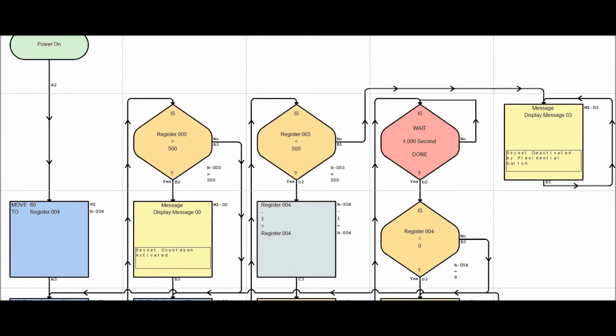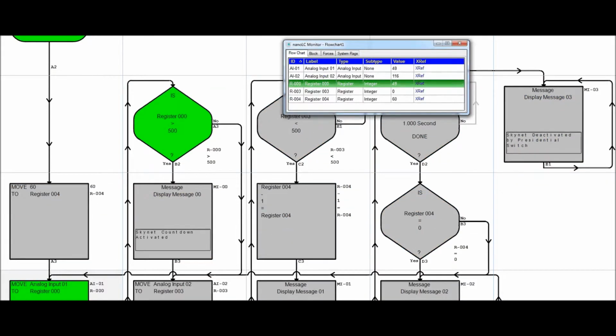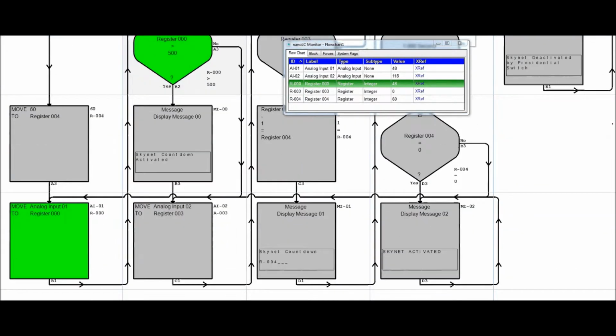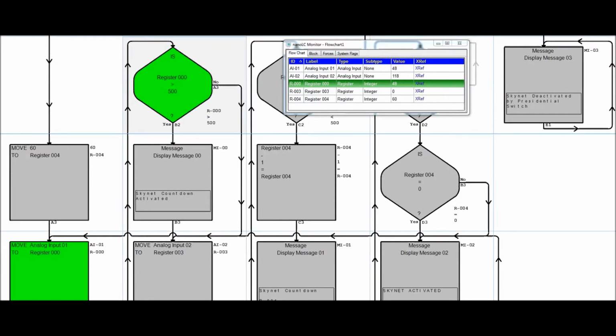So up at the top, you need to click download and go once you have it correctly connected and configured. And so right now you see that it's pretty much stopped at these 2 blocks. The reason why they're both green is because it's cycling so quickly between them, going back and forth. And this is waiting now for the output LED saying that all 3 conditions are met, and waiting for that signal. So I'm going to go ahead and start that signal.